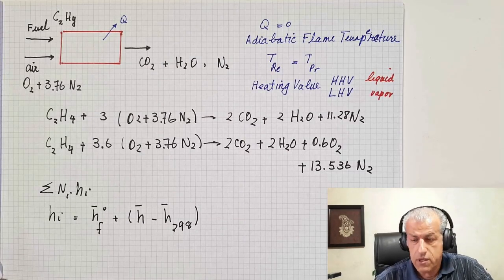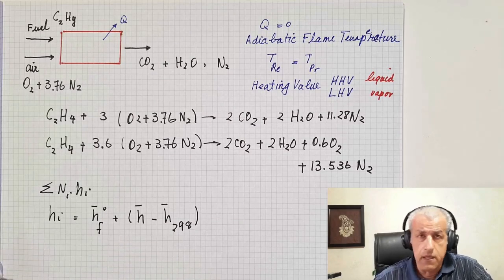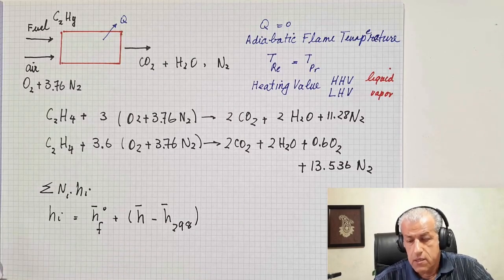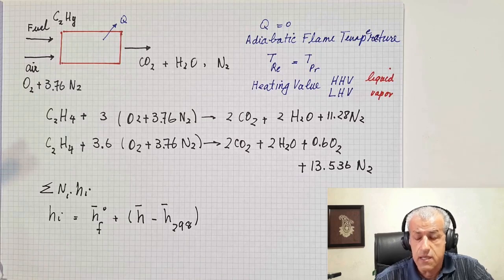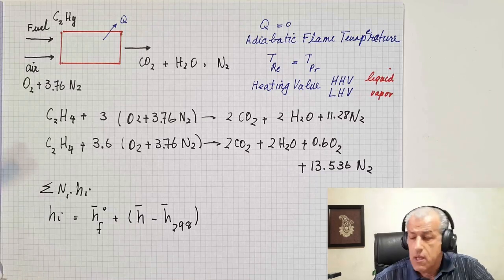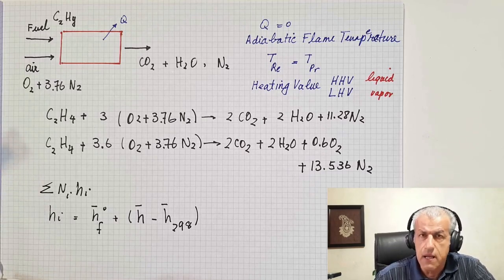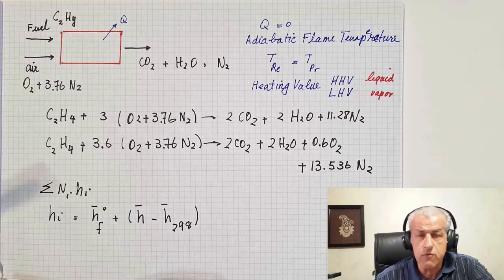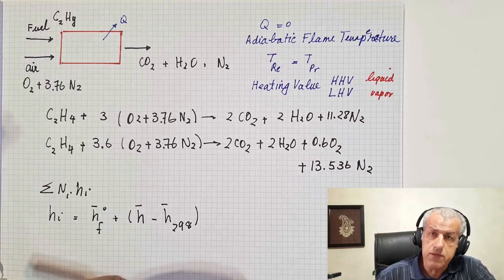You see, quite often, say in gas turbines, what we need is not a cold combustion product since they enter the turbine and higher temperature is desirable. So, in fact, a high heating value and liquid water in the products is irrelevant. Low heating value would be more relevant to the problem.